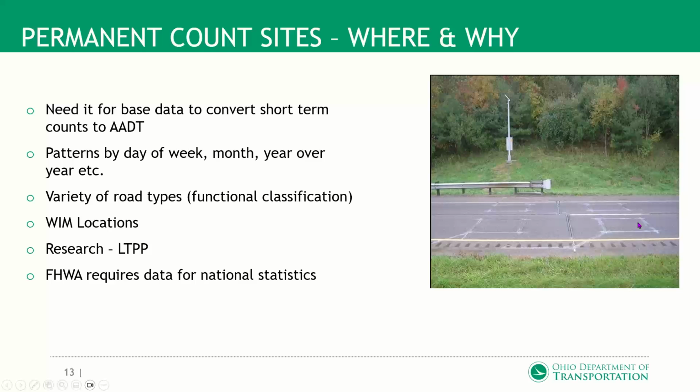So this is not the best station, but it is pretty typical of what you see out there. Our most common layout is a loop. Now loops are easy, they're not a big deal. Anyone could install these pretty well, but by golly, they better make them square and perpendicular or the data gets wonky. These straight lines here are called a piezo, and then another loop. This is a very typical in-pavement layout: loop, piezo, loop.